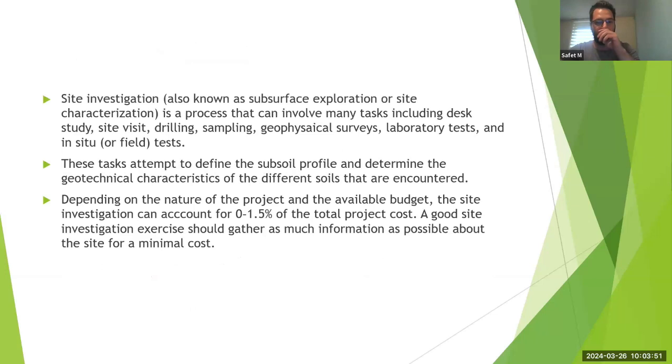So site investigation, also known as subsurface exploration or site characterization, is a process that can involve many tasks, including desk study, site visit, drilling, sampling, geophysical survey, lab testing, and a bunch of in situ tests, depending on what kind of structure we are dealing with. These tasks attempt to define the subsoil profile and determine the geotechnical characteristics of the different soils that we encounter. Depending on the nature of the project and available budget, the site investigation can and should be between 0 and 1.5% of the total project cost.